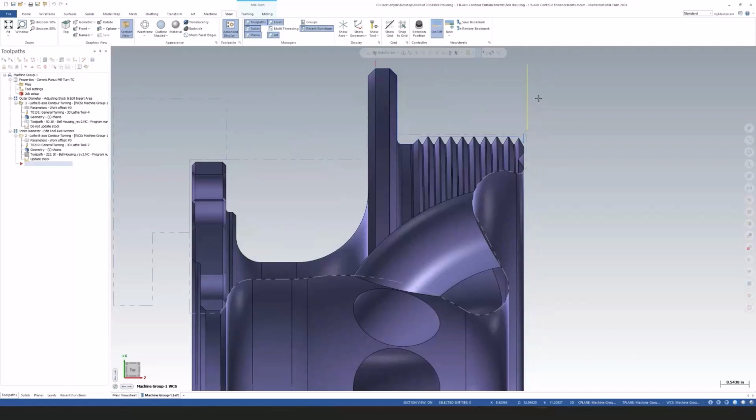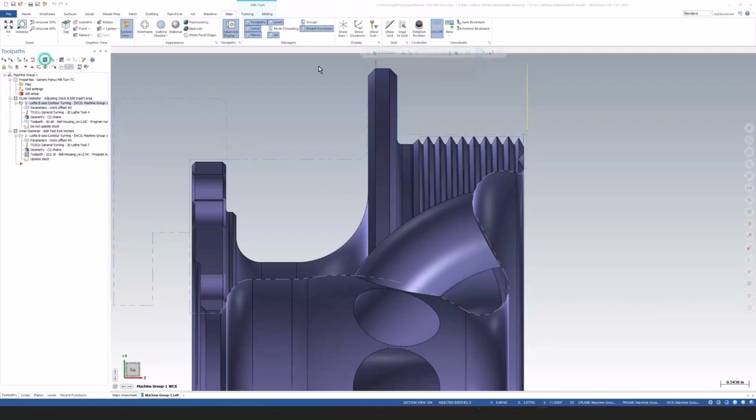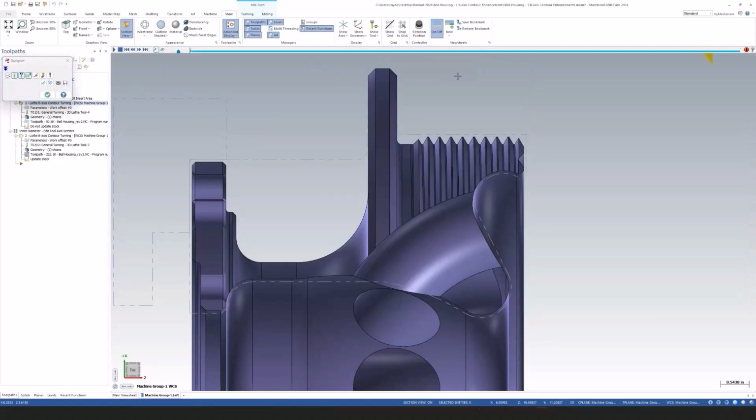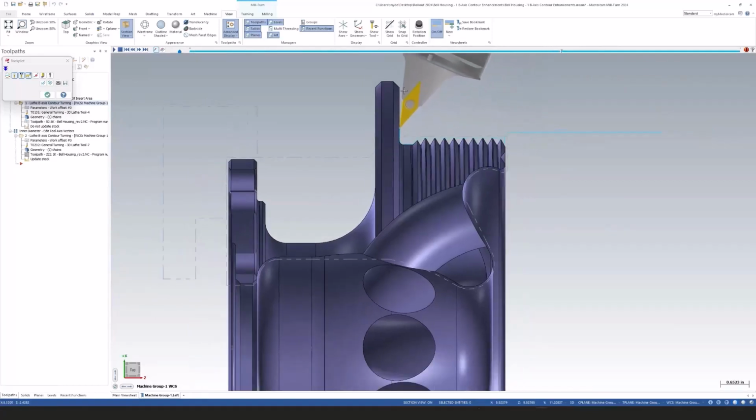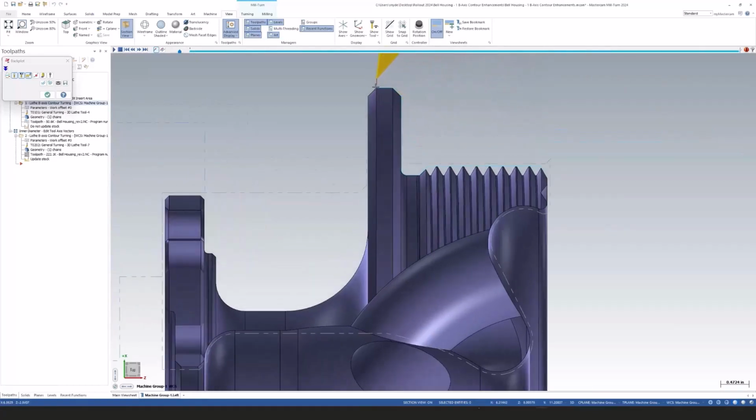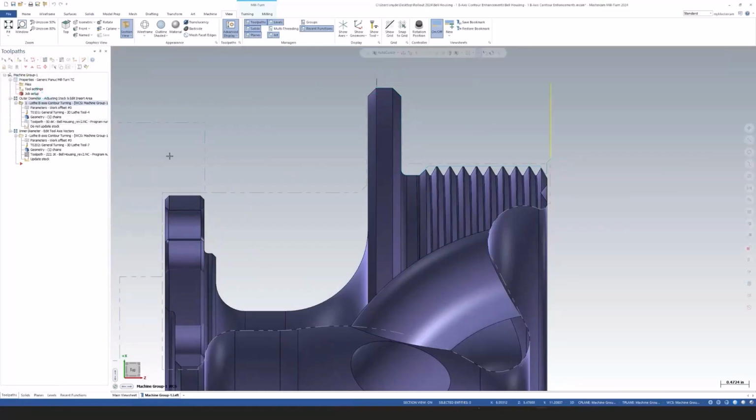So a B-axis toolpath will rotate the tool as needed to clear and reach anywhere it needs to reach. So for this one, it's set up as an automatic. We'll just backplot it and see where we're at and what we may need to do to it. So far so good. It's approaching from the outside, from the right side, but then it sort of plunges in. It does rotate nicely around and cut everything pretty well, but I've got a few changes I need to make.